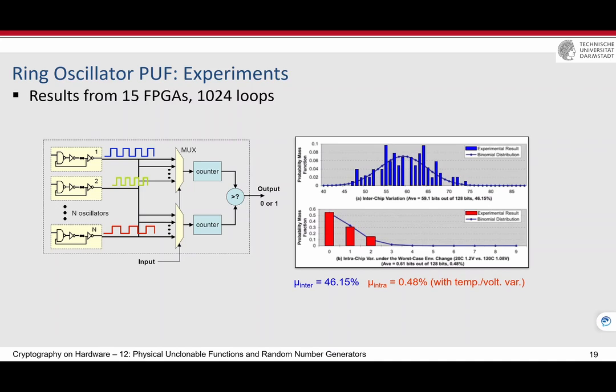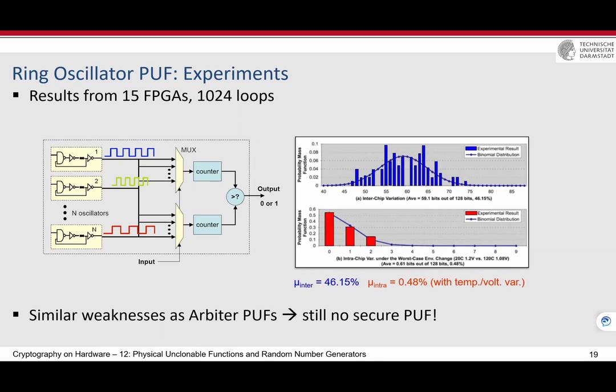You need to build this. We will deal with that later. It's easy to implement ring oscillators in FPGAs using the lookup tables and inversions and so on. But of course, it can also be learned, because it's not a super complicated machine, and there are not many parameters. In machine learning attacks, if you have enough layers and enough challenge and response pairs, then usually you can learn the behavior of the device with a high prediction accuracy.